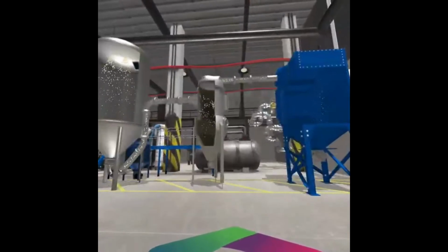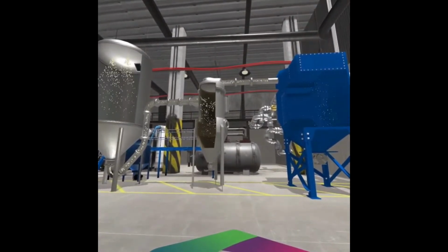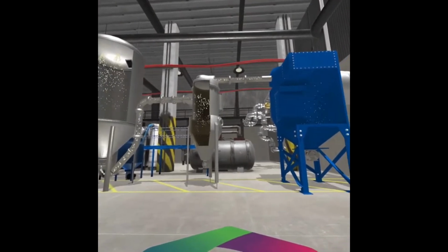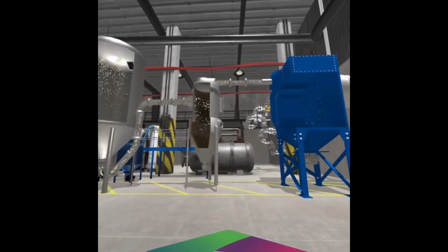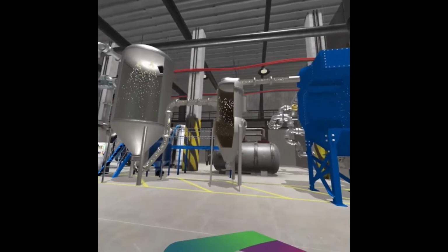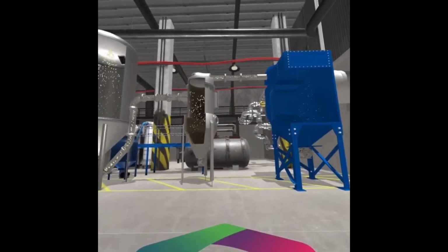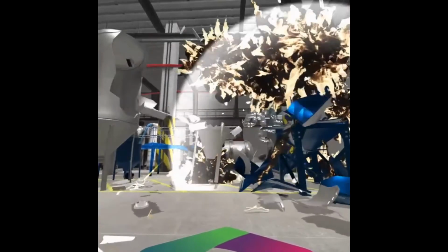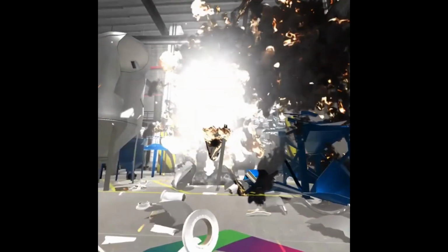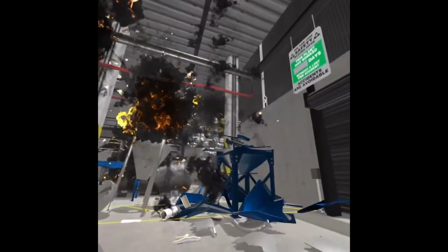The process appeared to be operating normally, but every ingredient required for a dust explosion was present. First, we had fine, dry dust. When this fuel was combined with oxygen and dispersed in a confined vessel, all that was needed was an ignition source, and in this case, in upset conditions in the form of an exothermic reaction from material built up in the spray dryer created the ember that triggered the explosion.